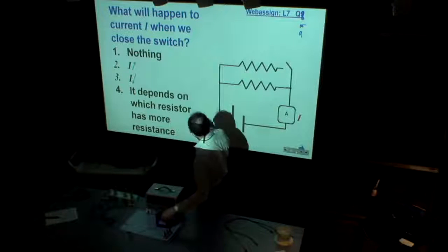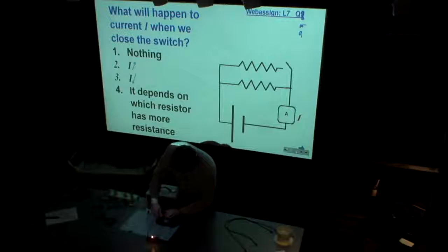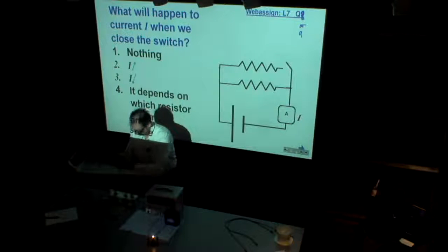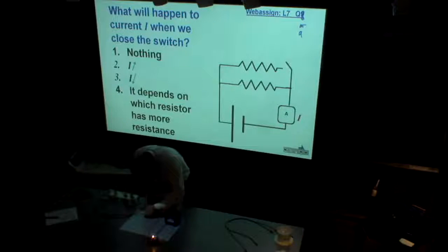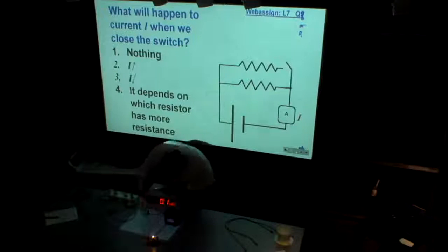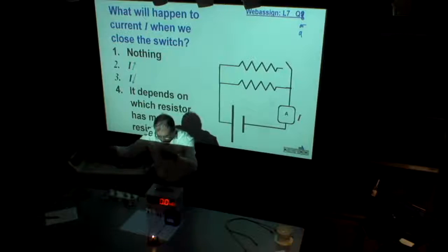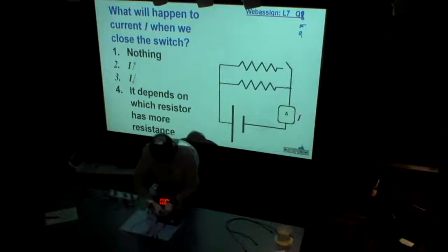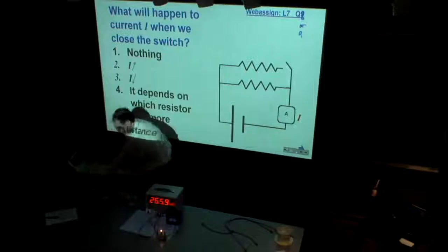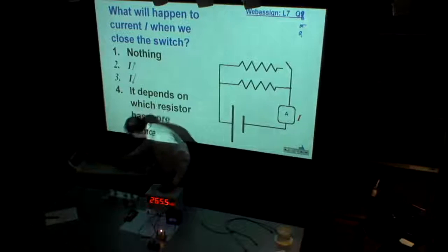But to do that, I have to build the circuit first. So I've got a battery, and I have a bulb connected to this battery, like this. And I have this device we call an ammeter. It's supposed to be plugged in, and now it is. So red, black-ish. I'm measuring electric current. Now I have a second bulb and a switch. How do I have to connect it? When the switch is closed, this bulb should be in parallel to the first one.